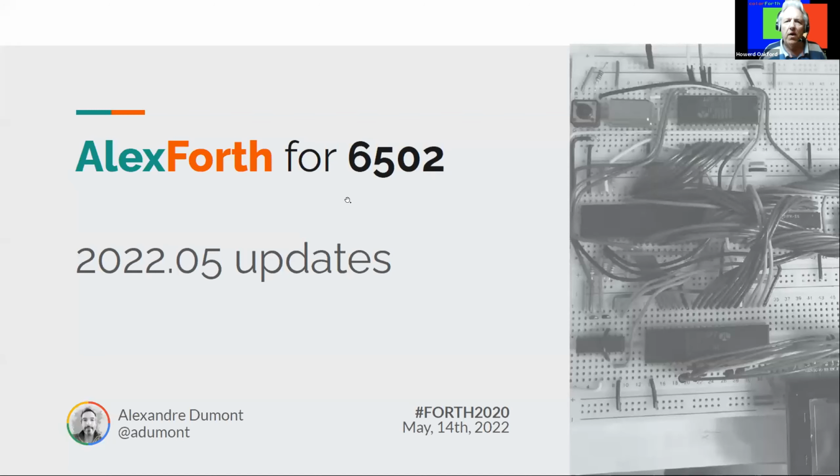Can I add a very quick comment? Yes. Have you tried? You said you had 2 printed circuit boards with shorts. A technique that somebody showed me a long time ago is take a 5-volt 100-watt power supply and power it up with that, because a short usually is a tiny little piece of copper that's got in somewhere where it shouldn't, and they usually just pop and it all works.